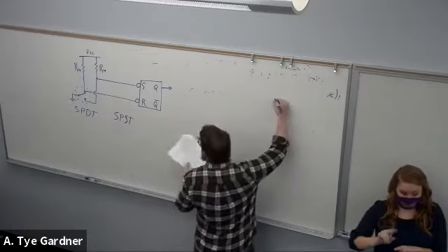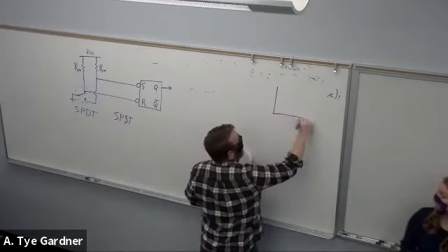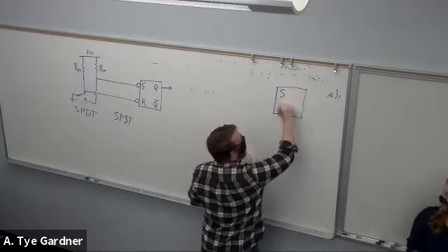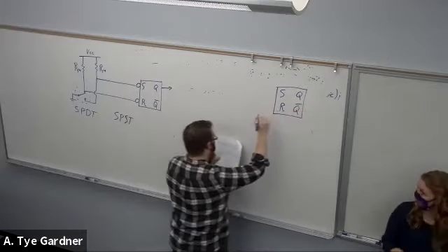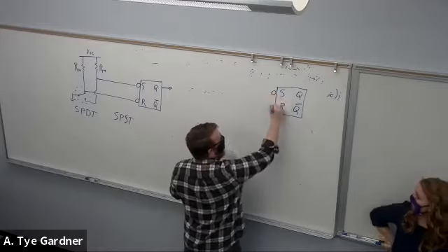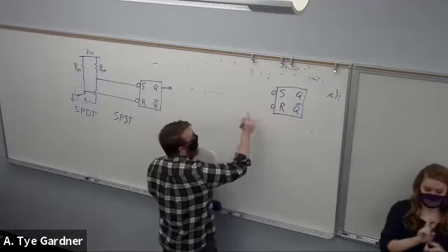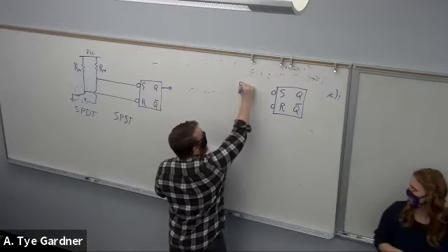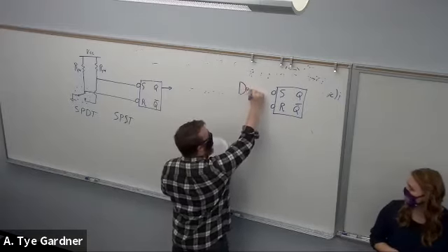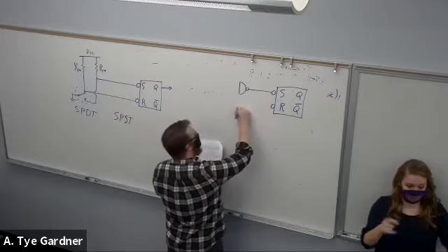So just like the other one, we start with an SR latch. I'm going to throw inversion bubbles on this, and you'll see why in just a second. And we're going to take advantage of this cross-coupling concept once again.